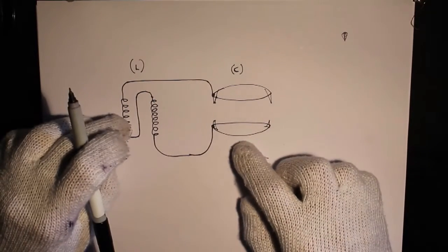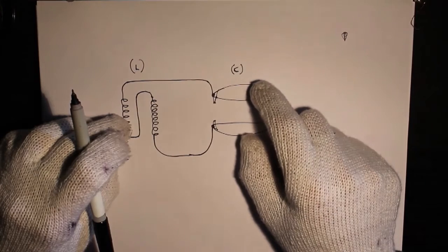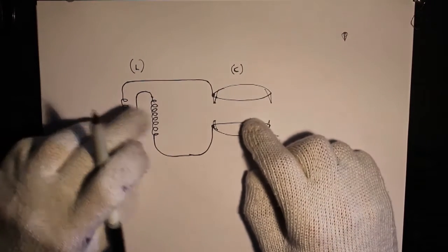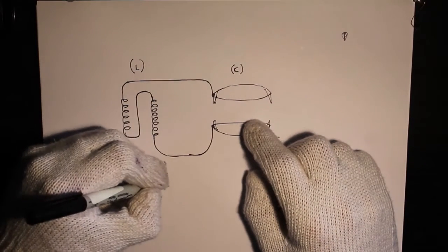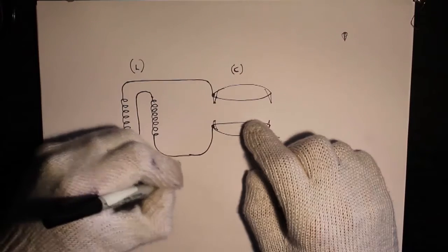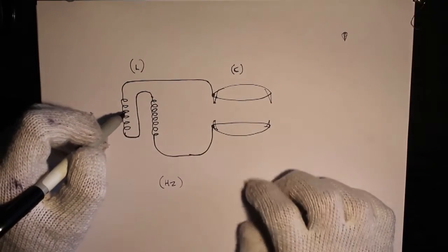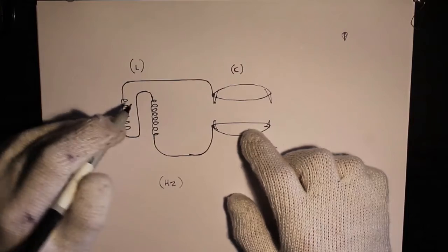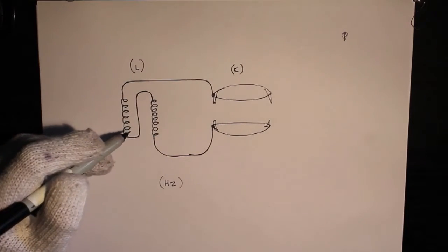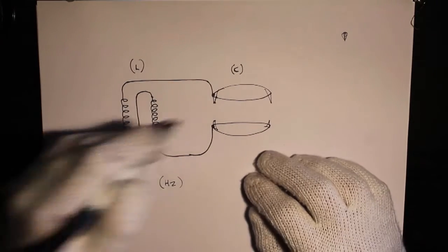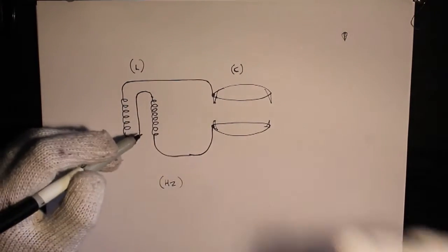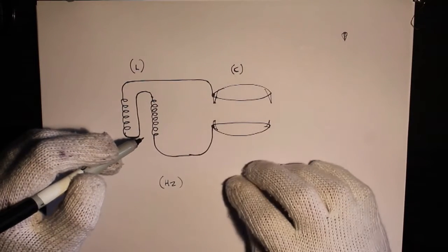By tuning the inductors and calculating what the capacitance is here, you can find out what frequency it is going to be. And you can test it with a frequency generator and an oscilloscope to find out its exact tuning, and that's really easy to do. It's very easy to do the electrical circuit oscillator here.